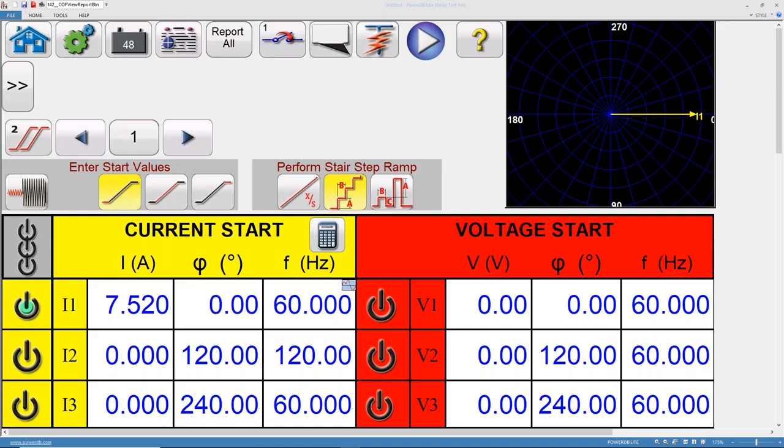What's really nice about doing a harmonics test with RTMS and an SMRT unit is that we don't have to use two generators. You don't need to stack two generators, so we don't need 4 cables to tie to this relay. We can do everything using the single current generator. The single current generator is going to apply our fundamental frequency along with a 120 hertz signal, stacked on top of the fundamental frequency of 60.